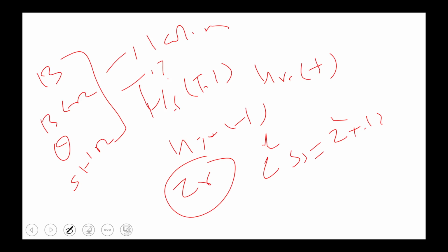Also the amplifier, whether EDFA or some other amplifier like silicon or germanium, should be considered. For the amplifier, you use an EDFA after 40 kilometers, 28 kilometers or 60 kilometers. The amplifier also has some SNR penalty and some loss.